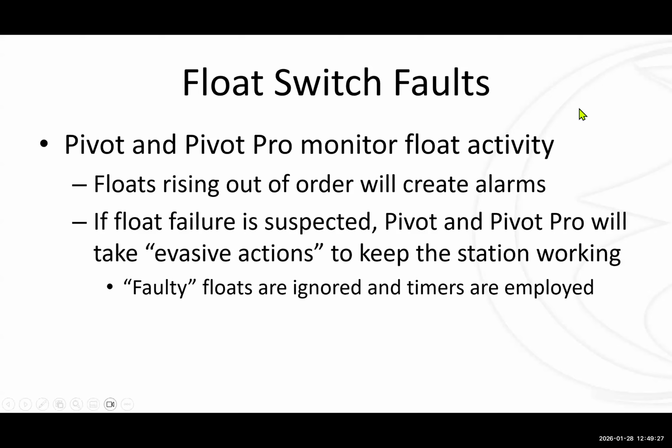So we have active monitoring of those float switches in the pivot systems. You're going to hook those floats, and it knows that stop should be the lowest float, and that above stop there's a start float or a lead float, and then above that is a lag, and above that is an alarm. And so if those floats rise out of order, then it will sound an alarm